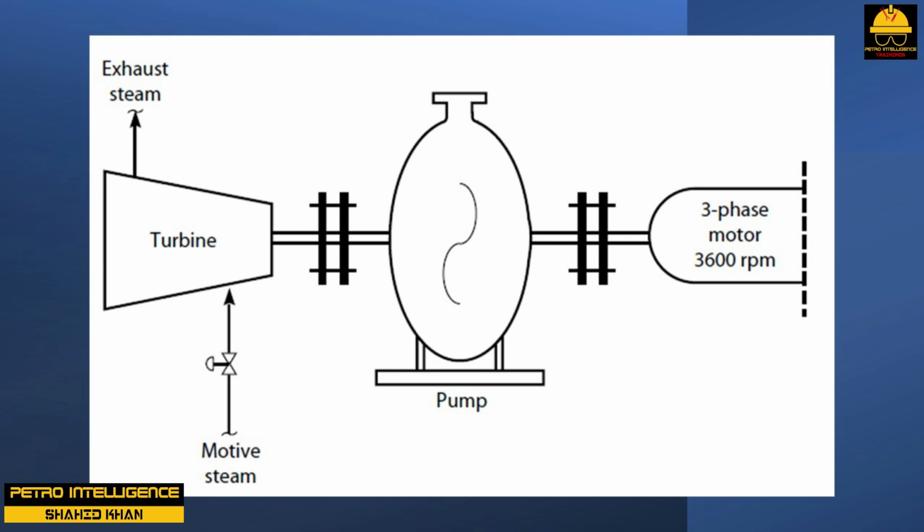The only way we can get more flow from this pump without reducing the pump's delta P is to raise the specific gravity of the liquid being pumped. If the liquid is cooled from 400 to 200 degrees Fahrenheit, its specific gravity will increase by about 10%. This will allow us to get the same delta P with about 10% less feet of head. This will allow the pump to run further out on its performance curve. The pump will now pump more liquid, and the flow of light gas oil to the hydrocracker could be, and was, increased from 17,000 to 23,000 barrels per day.